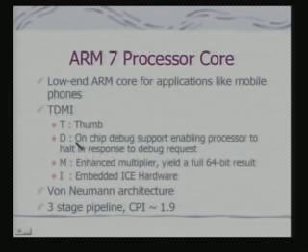You have these variants of the ARM core, which are indicated by the letters T, D, M, I. T is basically Thumb mode, that means you have an embedded 16-bit processor inside the 32-bit one. So, you can switch from ARM to Thumb and back.